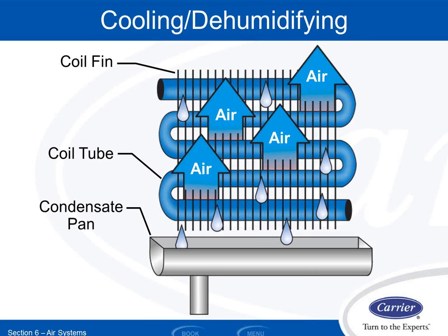If you guys have never seen a coil, if you were just driving down the street and you see one of those green electrical transformer boxes sitting on the ground every so many blocks, they always have those protrusions sticking out of them. That's to give it more surface area so it can reject heat more. Heat transfer is very often a function of surface area in addition to air motion. So if I want to have more heat transfer, I need more surface area. So just serpentining a coil through here would only do a certain amount of heat transfer. Putting all these fins on here does the rest for me.